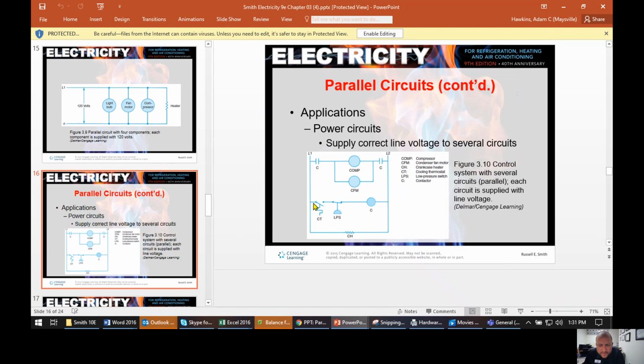And then you've got a couple of things in series with that coil, but they're both switches. So in the case of the one on the left, you can look at your reference. That is a cooling thermostat, which just would mean that it is a make on rise thermostat. If you'll notice the way that that little symbol is drawn, that's just a symbol for a thermostat.